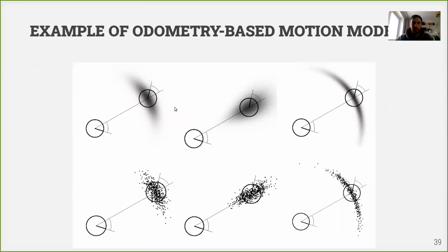So usually it is called banana shape distribution. And actually taking into account that first rotation is imprecise, travel distance is imprecise, and the second rotation is imprecise, with different motion noise parameters, we can get something like this. These are three types of noise of pose distribution of our robot after a single motion. So even though we were quite precisely sure where we are in the first place, after performing some motion, we will get a probabilistic distribution of possible robot poses.